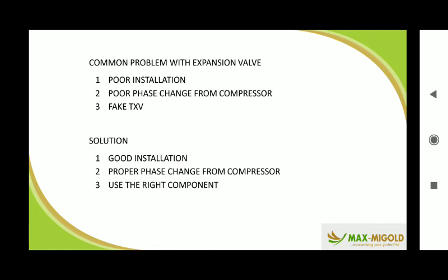So I always recommend you as a facility manager to have a certified vendor for all your product. If not, sometimes to determine which is fake and which is original might be difficult. Then solution: good installation, proper phase change from compressor, and use the right component. That is TXV. That TXV stands for thermostatic expansion valve. Thermostatic expansion valve. But the normal name is expansion valve.